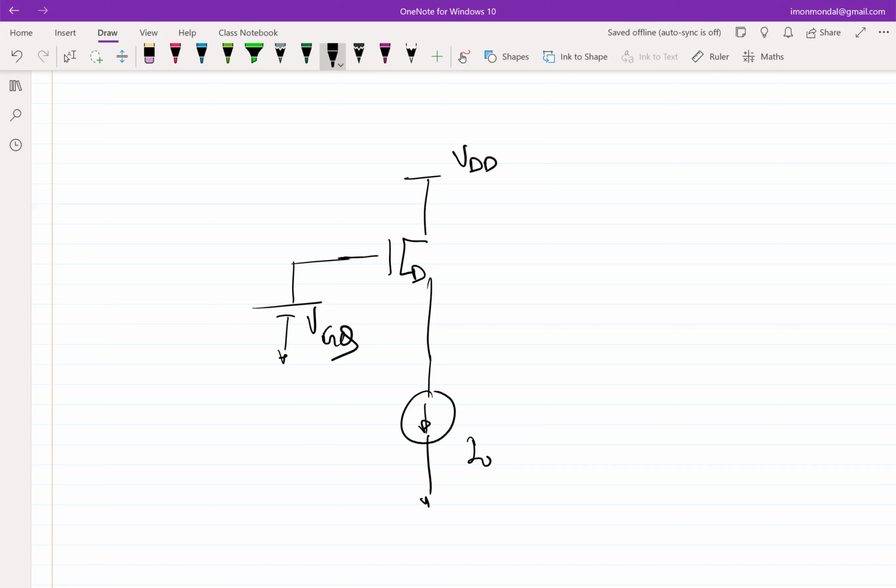The question is, if I have a box and I am trying to figure out whether the looking-in impedance is high, whether it's a current source or not, what am I looking for? Impedance has to be very high, right? Infinity, ideally. But in the absence of too much information, it has to be high with respect to whatever I have connected. So now, given that you know what a transistor looks like, what can I do if I want to replace this current source with a transistor?